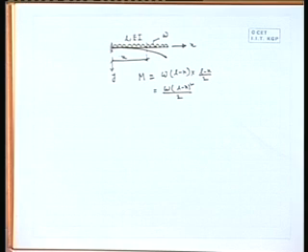Now, we have to put some sign here. At this moment, you have to decide which sign convention you will take as positive. If you take sagging as positive, it should be negative, because it will give a hogging type of moment. So, if we follow the same thing, it will be minus. I think this part is clear, the bending moment expression.